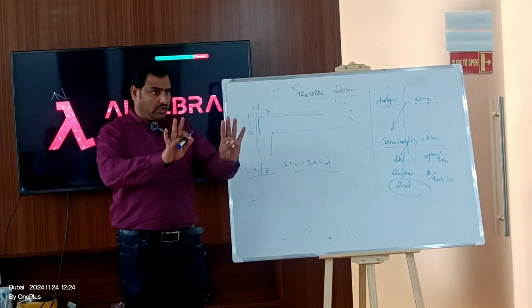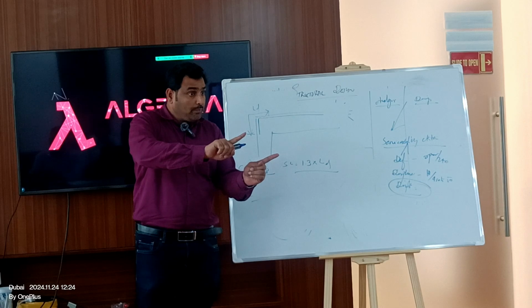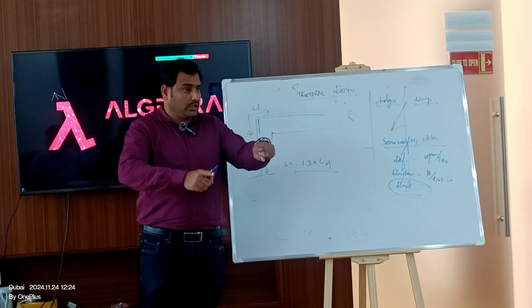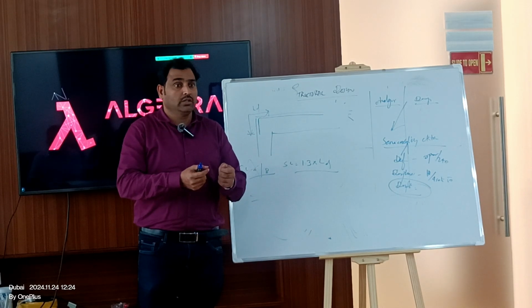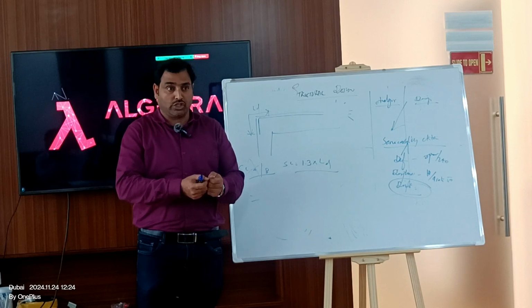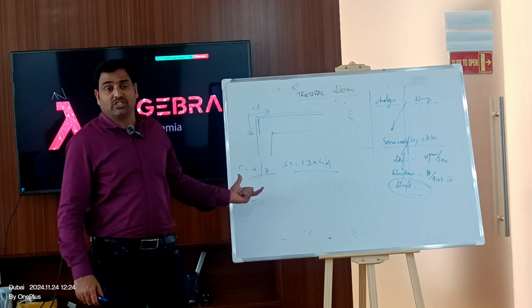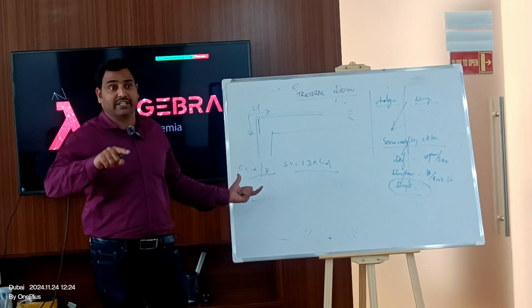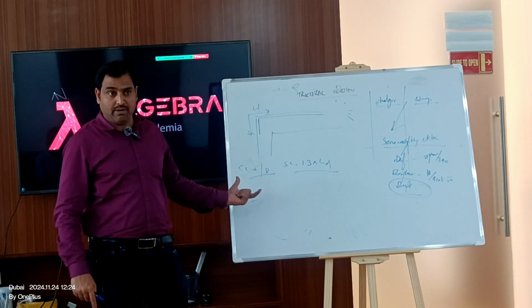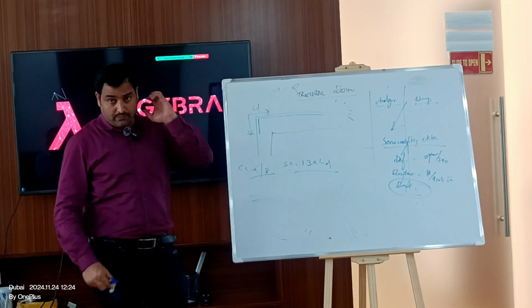Same rebar, don't confuse yourself. Only where exactly you will be using this: between the bond, between the structural loads. So you are always using class B rebar. Sometimes in the structural details you will see category 1, category 2 rebar. It's all class B rebar.